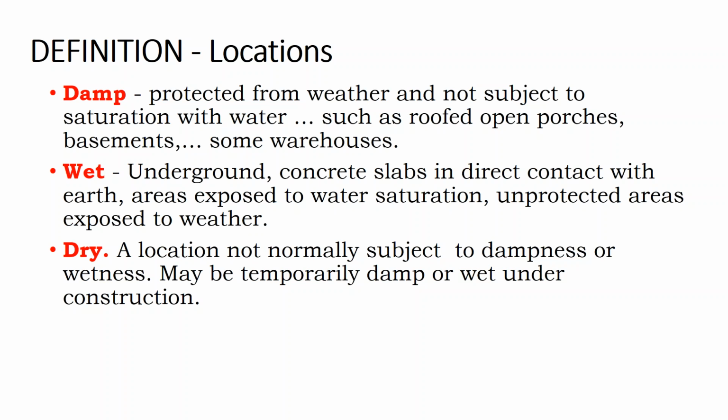And so the point is, going back to this solar industry specific cable, we're talking about wet locations and dry locations, because you might think, well, a wet location is more rugged than a dry location. Dry locations are wimpy. They're for inside your house, and you don't need to worry about them. With dry locations, you're using cheaper traditional building wires that have really thin jackets. You don't need to worry about moisture.